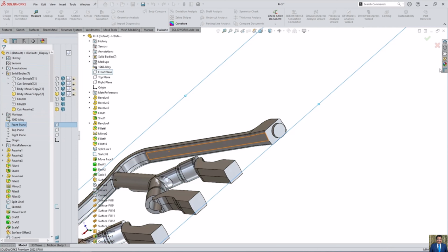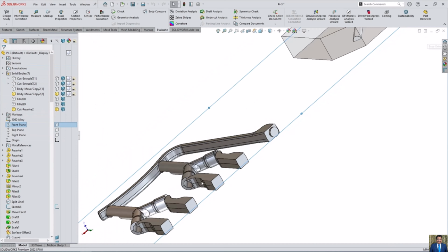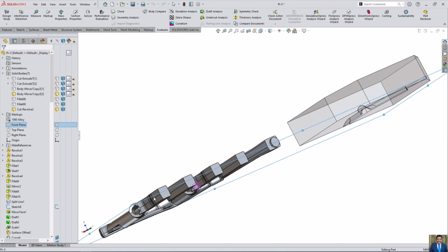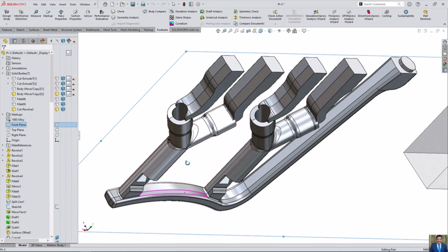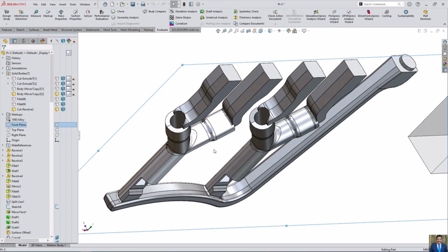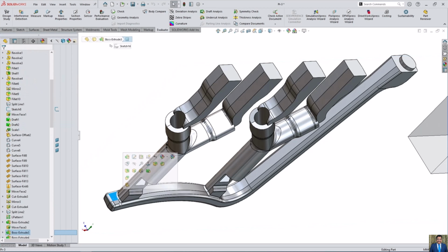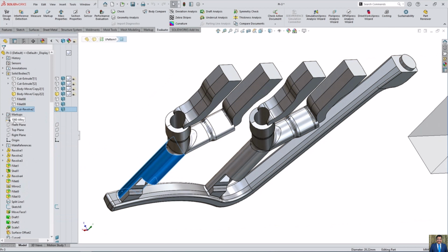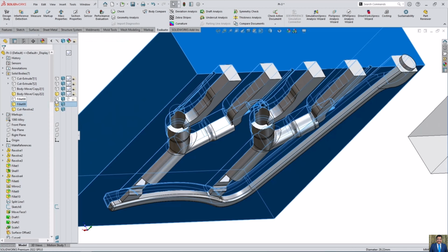And now we know, because when we create an injector pin, because the piece looks symmetric, sometimes we are not sure on which side it sticks. And we leave a different draft here than here, and also a different draft here, and also we have more material here, and it sticks on another side. And on another side we need to have an injector pin.